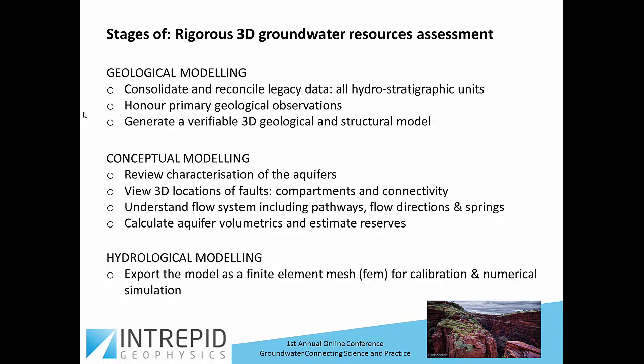There are three stages of rigorous 3D groundwater resources assessment. Geological modeling, in terms of consolidation and reconciliation of legacy data, including all the hydrostratigraphic units, honouring primary geological observations, and finally generating the verifiable 3D geological and structural model. Conceptual modeling is at the heart of stage 2, and that means you're ready to review the characterization of the aquifers and view in 3D the locations of faults, fault compartments, and their connectivities.